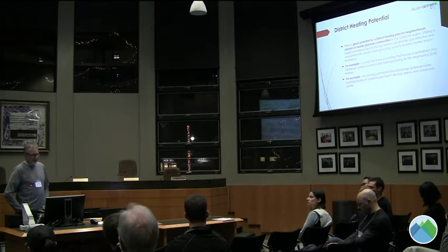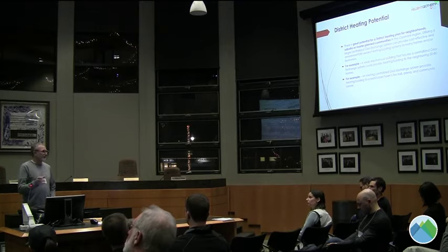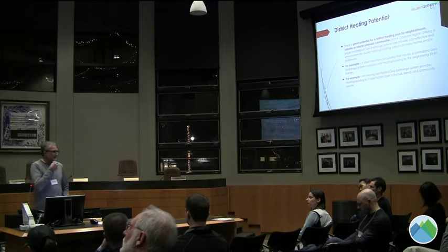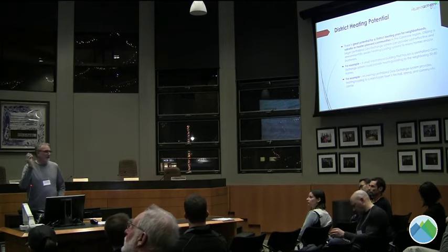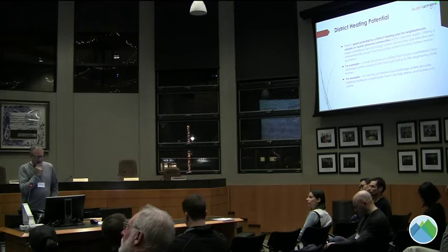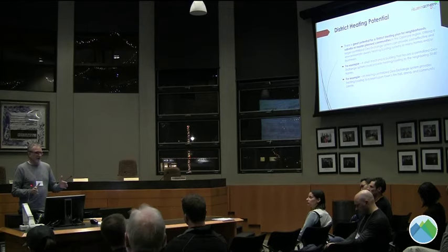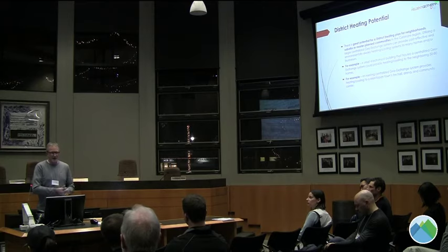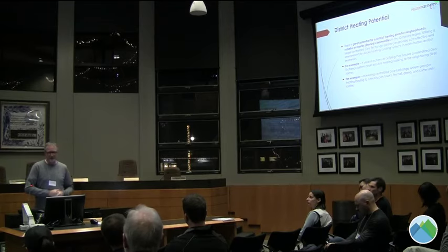Okay, I just want to touch on district heating potential. For Canmore, that's great for the infill building with all the fourplexes and fiveplexes that are going in. A central heat pump can heat all of them, basically, very efficiently. Another example that we could do here would be a new neighbourhood with a small centralised building, the size of say a double car garage, that would house the geothermal system, and that would be enough to heat a small neighbourhood of 50 to 80 homes, and it would be very, very cost effective.